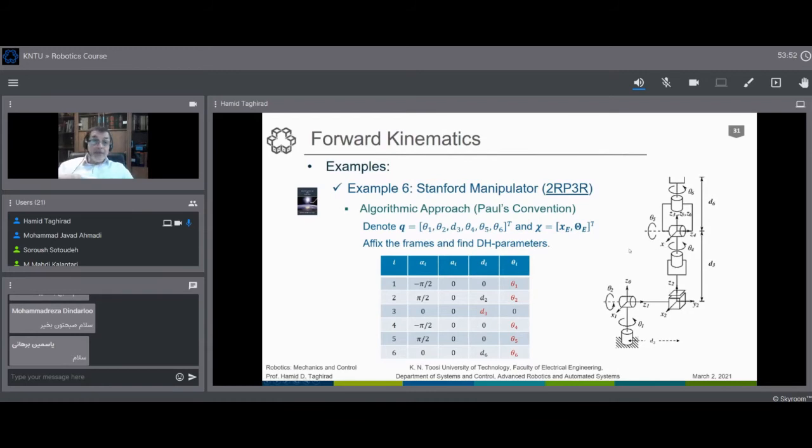Why is this happening? The reason is that we have a prismatic joint and a rotary joint on top of that. If we have two rotary joints on the same axis, it is not useful, because they will be redundant. I can't say nonsense, but it is not usual to do that. But here, since we have a prismatic joint and a rotary joint, it is possible to do that.